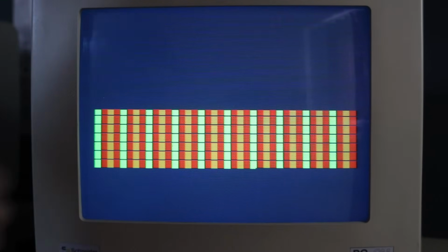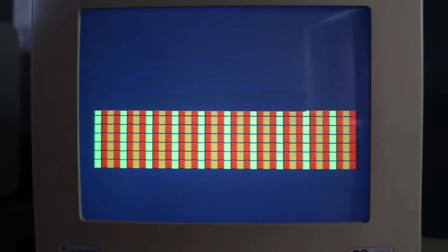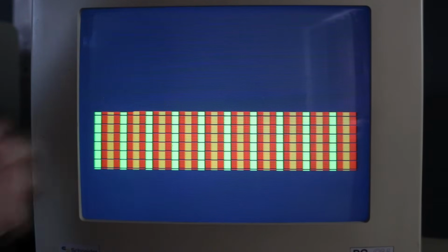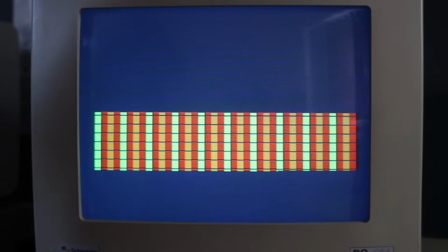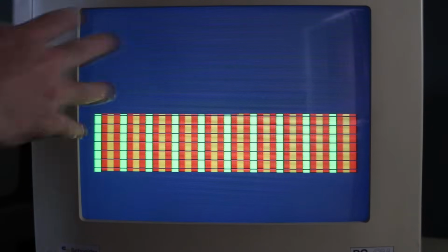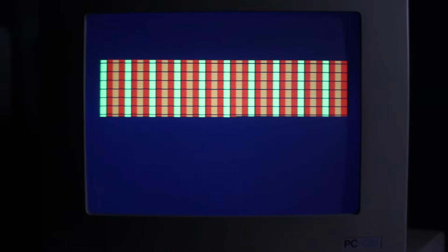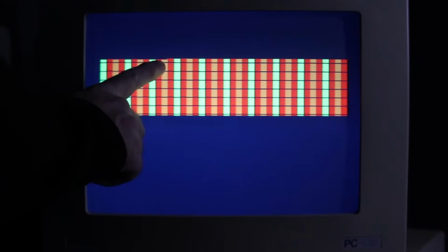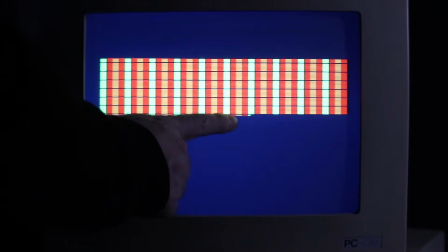Now I'd be really surprised if they managed to come up with a complete CGA implementation that was totally flawless, and that's what we hope to find out for the first time. But to do that, I'm going to need to check all of the different registers for lots of different values. Well, I just noticed something interesting that I overlooked. This change, due to changing the vertical displayed register, is not taking effect line by line or even character by character.